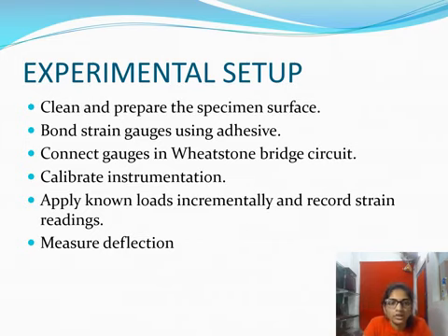Experimental setup. First of all, clean and prepare the specimen surface, mount the strain gauge using adhesive, connect the gauges with the Wheatstone bridge circuit, calibrate the instrumentation, apply loads incrementally, record the strain readings, and measure deflection.